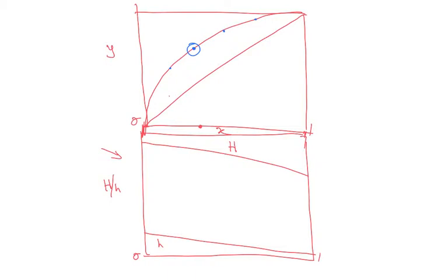And how do you do that? This point has an x value, right? So to locate that x value, you just project it down to the small h curve, because that's the liquid phase. Now, for the y value, you draw a horizontal line, let it intersect the reference line, and you drop that to the capital H curve, and you'll get the y value there. When you join these two points on the enthalpy concentration diagram, that's how you get the tie line.